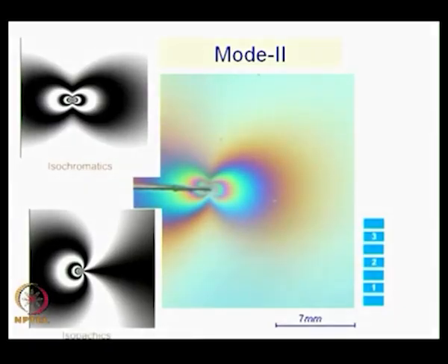See, when you come across some photoelastic fringes related to fracture, you can associate what type of mode of loading it represents, and this also gives you a comfort that what we have been discussing as Westergaard solution are indeed good, because from fracture mechanics point of view, what happens in the near vicinity of the crack tip is more important than what happens at distances away. From that point of view, the Westergaard solution is still quite useful. The singular solution itself is good enough when you are looking at the mode 2 situation.